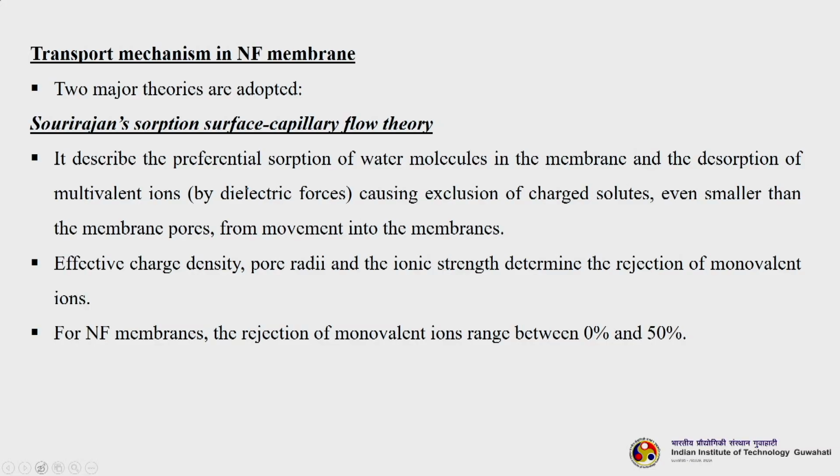So, in the Sourirajan sorption-capillary flow theory, it describes the preferential sorption of water molecules in the membrane and then the desorption of multivalent ions by dielectric forces, causing exclusion of charged solutes even smaller than the membrane pores from movement into the membranes. That means the water molecules are getting sorbed inside the membranes, okay.